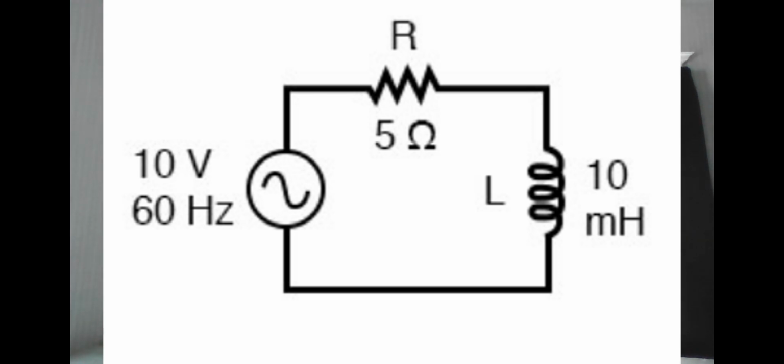We know the phase of a resistor's resistance is 0 because the voltage and current are in phase. And we know the phase of an inductor's reactance is 90 because the voltage and current are exactly 90 degrees apart from each other. For the resistor, the resistance is given right off the bat. And for the inductor, we have a formula for the reactance, which was the X sub L thing.